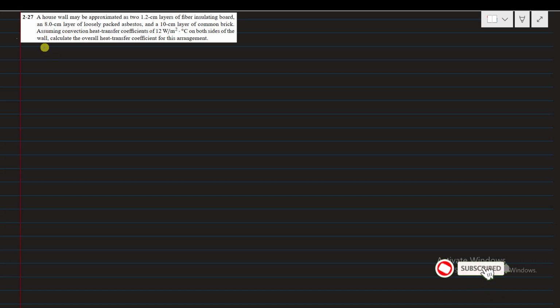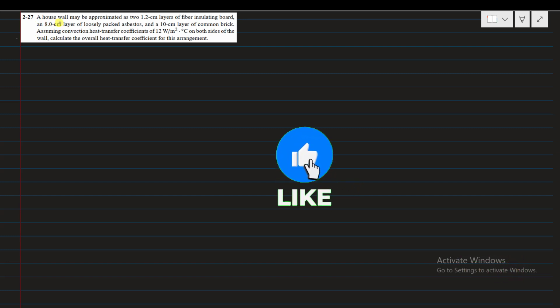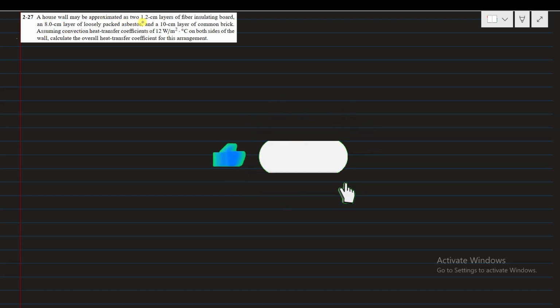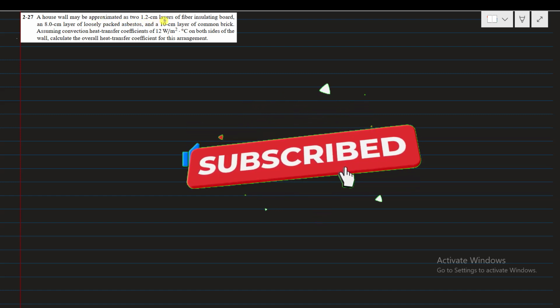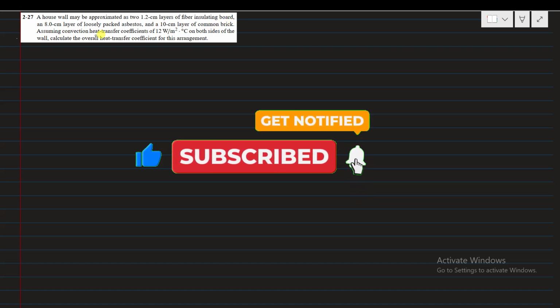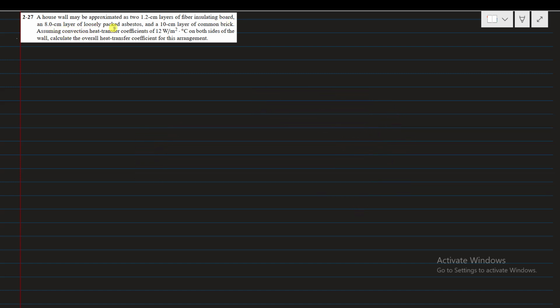Hi viewers, in this video we'll solve problem 2.27 from the book Heat Transfer by J.P. Holman, 10th edition. Here is the statement of the problem. A house wall may be approximated as 1.2 centimeter layers of fiber insulating board, an 8 centimeter layer of loosely packed asbestos, and a 10 centimeter layer of common brick. Assuming convection heat transfer coefficients of 12 watt per meter square per centigrade on both sides of the wall, calculate the overall heat transfer coefficient for this arrangement.